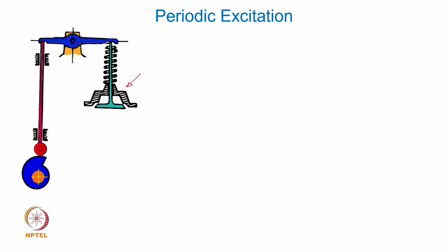the valve will open gradually as the cam rotates counterclockwise in this fashion, and then it will push the follower up, and the fuel mixture will be let in gradually. Then during the compression stroke we expect the valve to close as fast as possible. So, there will be a sudden closure of the valve, and then no movement of the valve till the next cycle begins, right?